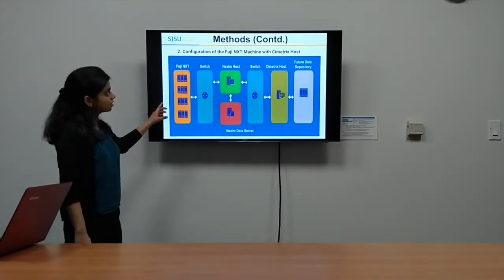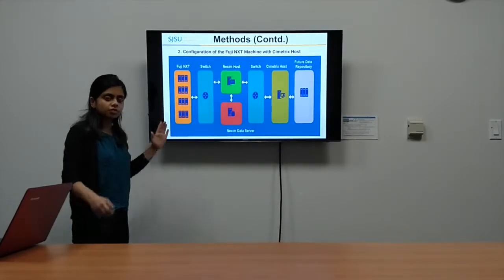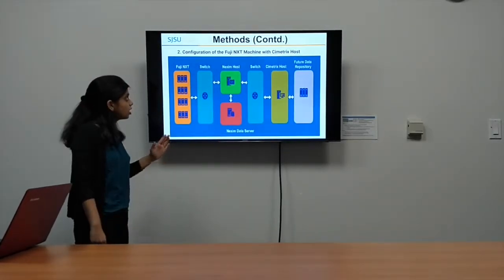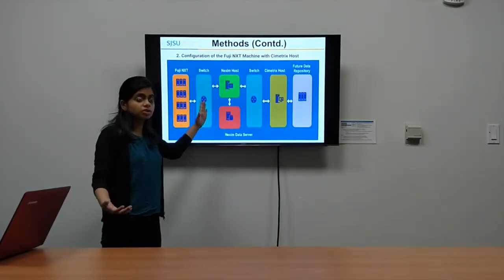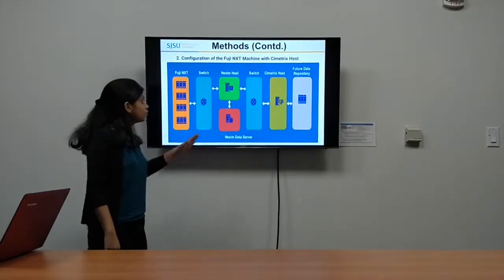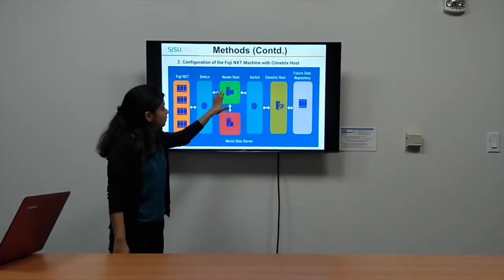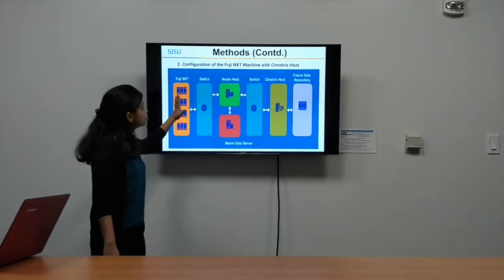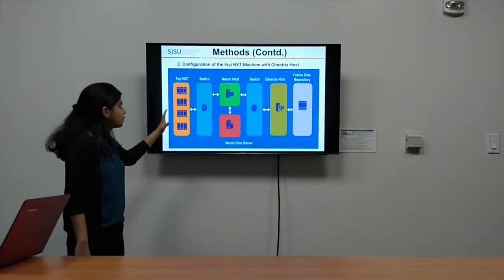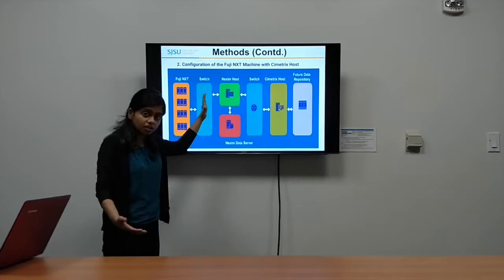And as this block diagram explains, here we have the Fuji NXT pick and place machine where we were placing the printed circuit boards. And there was a switch, in networking language it's called a switch or a hub, which configures the NXT pick and place machine to the Nexim host, which was another software that extracted SECS/GEM compliant data from the Fuji NXT pick and place machine, through the switch or the hub.